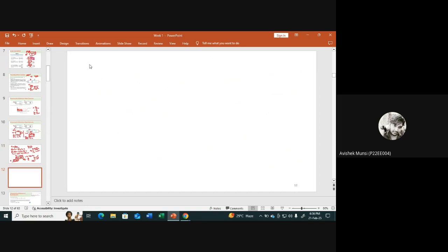Let me apply the amp-second balance, or charge balance, you can also say that. So I said that the capacitor current during the turn on time plus the capacitor current during the turn off time will remain 0, right?